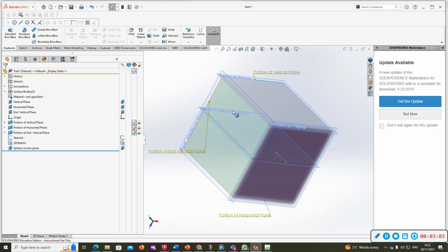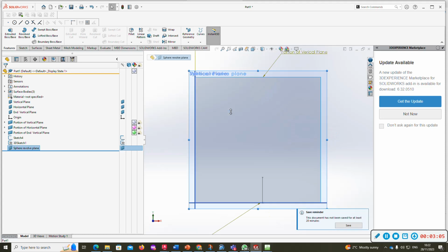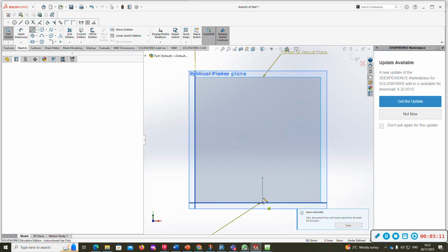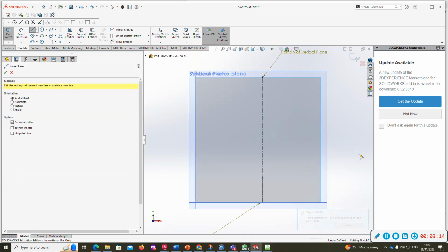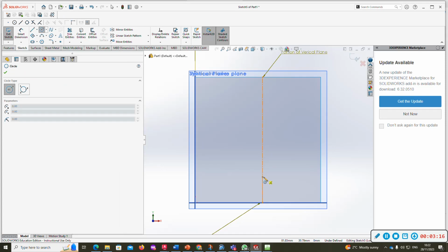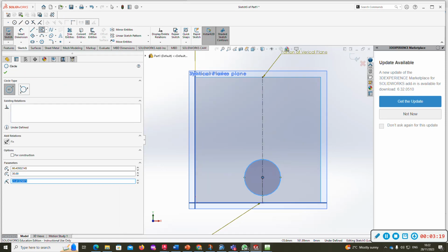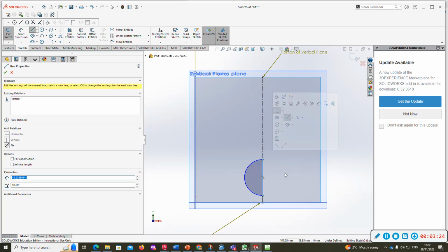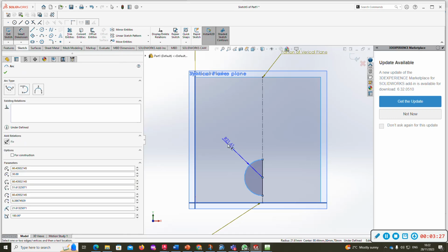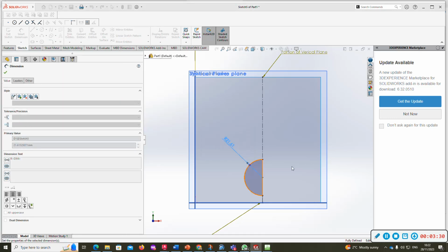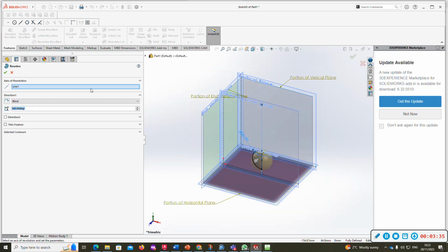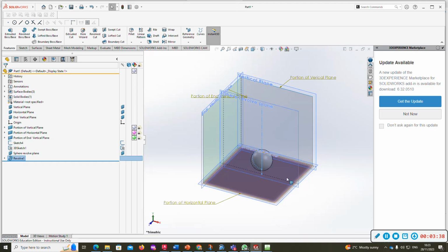Okay, now I'm going to click sphere revolve plane, control 8, I'm going to press sketch, center line, start from the bottom, go up to the top, circle, so draw a circle, trim entities, cut away half the circle, L for line, close it, D for dimension, radius 20. And the semicircle goes black. Features, revolve boss base, we've got a sphere there. We'll rename that the lollipop.